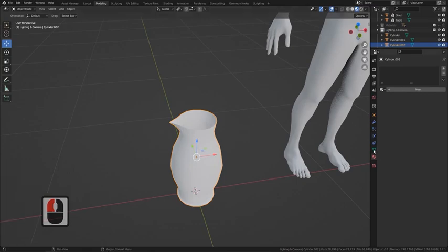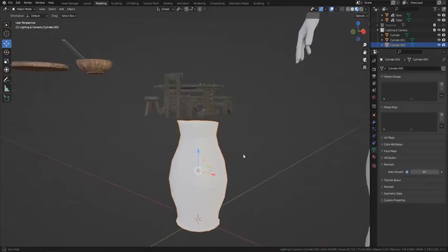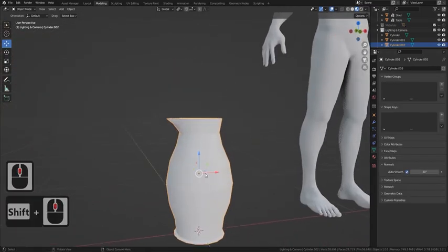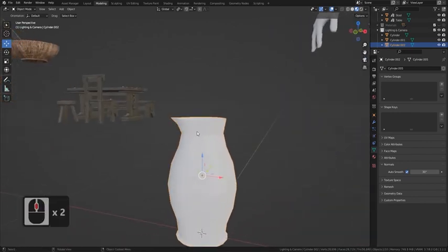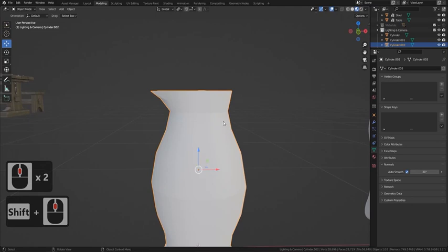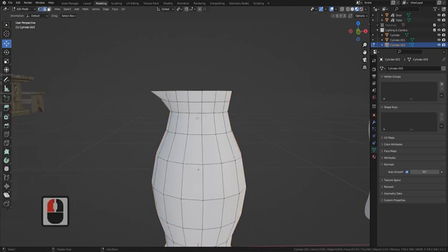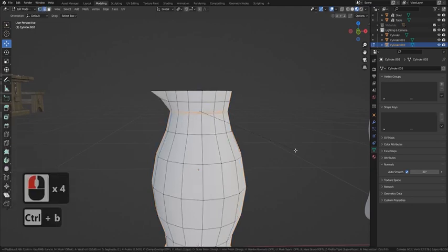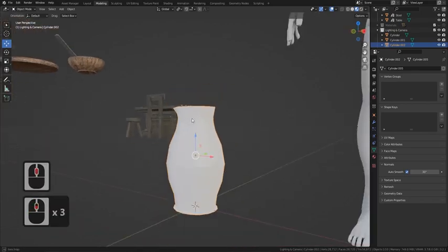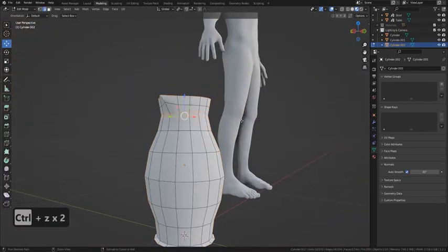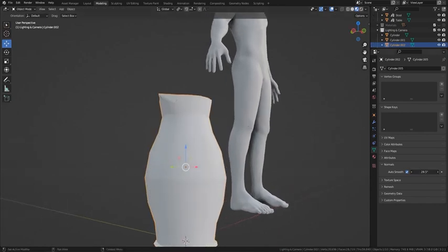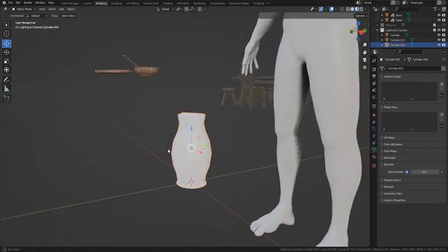Let's right click and shade smooth, bring on our auto smooth, like so. And you can see we've got a few lumps and bumps and things like that. You might not want these in there. If you want these smoothing out, the best thing you can do is just come in, grab this for instance, press Ctrl B, and you'll see now that you can actually smooth those out. All right, so I'm happy with that except this bit. I'm just going to go back because I don't actually want mine smoothing out. But if we turn down this or up, you can see now we can get rid of all those lumps and things like that. All right.